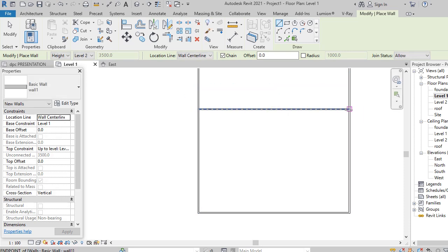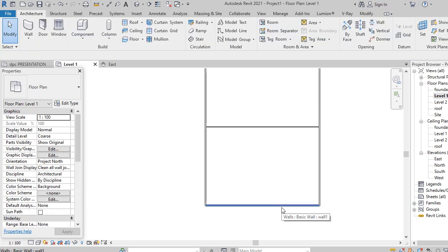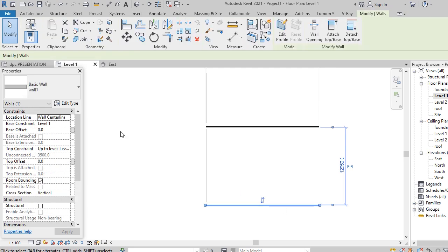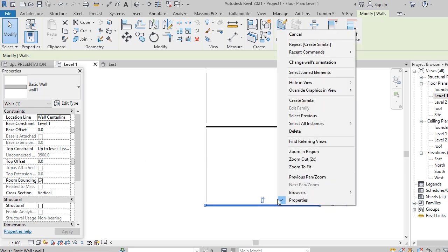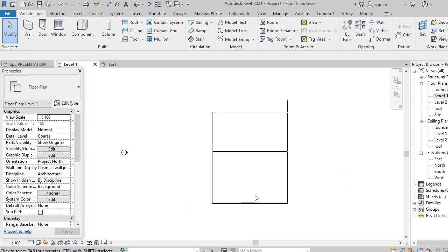Select it, it means the next wall you're drawing has the same properties as this. So if you have that of 225 millimeters thick, all you have to do is select that of 225 millimeters thick after you have edited and duplicated the wall and given it a different thickness. After making the first drawing, you can select and then create a similar type of wall. In that way, you can just be moving fast in your modeling.